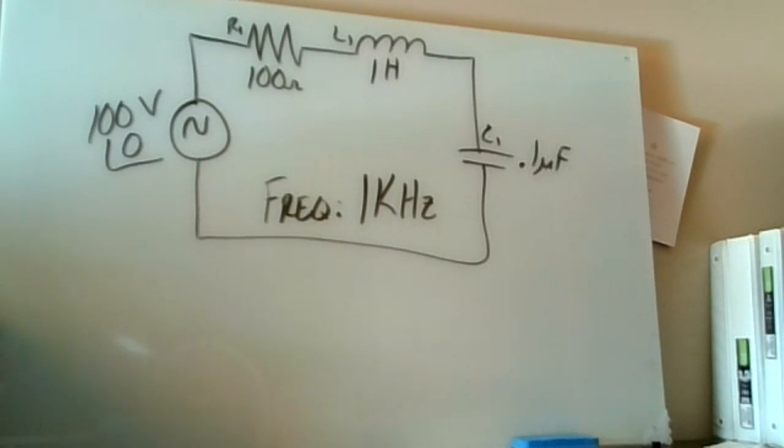First thing I'm going to look at is what type of voltage do I have? What form is it in? If it's in phasor, I'm good. If it's in sinusoidal, I have to convert it to phasor. Then I look: if it's in phasor, do I have a frequency? If it's in sinusoidal, do I have a frequency or a value for omega? I need one of the two.